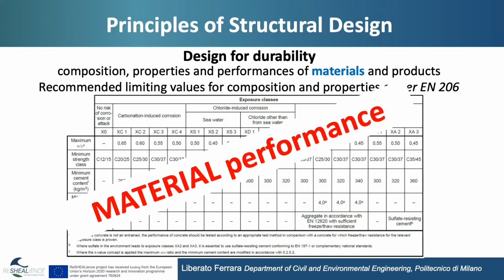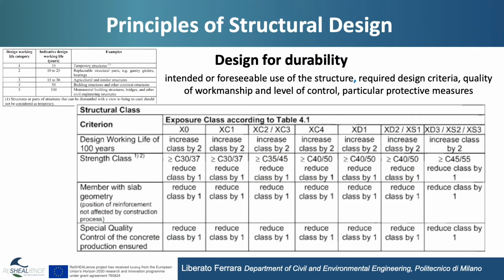Then we also are addressed to go for structural performance requirements. So first of all, to think of a structural class. Generally, our structures are designed for a service life of 50 years. So it could be a structural class number 4 according to the table in the top left of this slide.